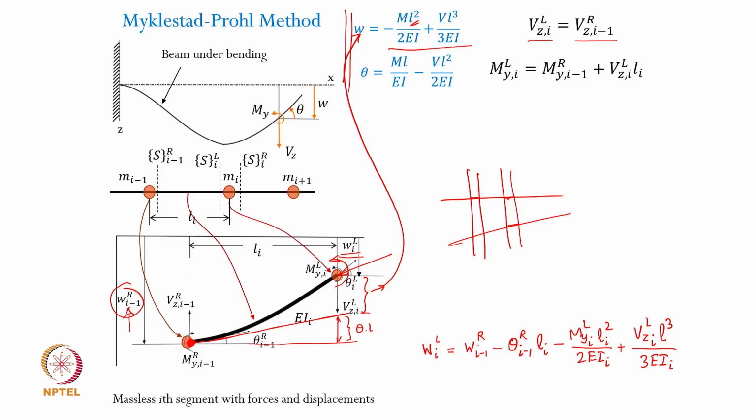In fact, theoretically you can also have different material. So if you have functionally graded materials, with material properties changing with the spatial coordinate, then you can in fact theoretically have different E as well. But this EI can pertain to the flexural rigidity in the ith segment, okay. So you can have subscript i representing that particular segment's property.